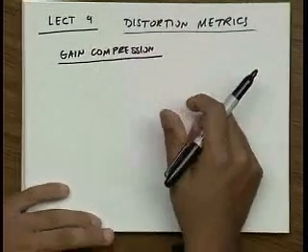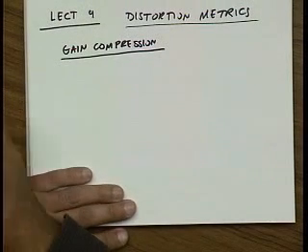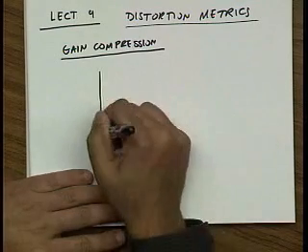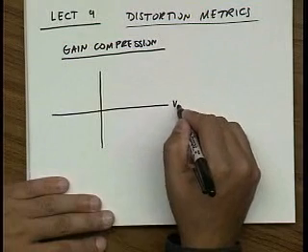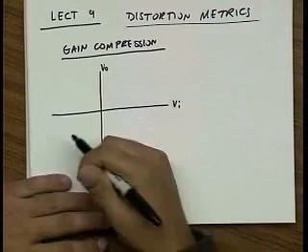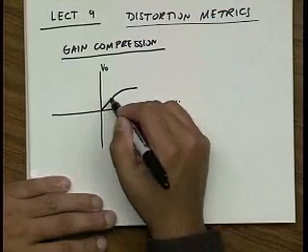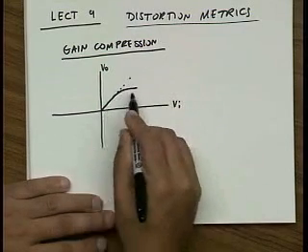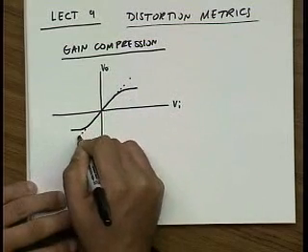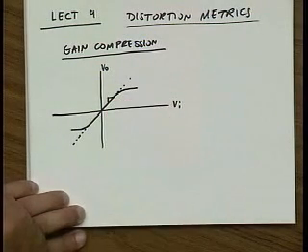Now the idea of gain compression is very simple. If you go out into the lab, in fact I encourage you to do this, take a commercial amplifier and plot the power gain. Well, first plot the output voltage as a function of the input voltage as you vary the input. So this is the input, this is the output. And this could be an AC signal, it could be a low frequency signal, but what you'll find, as we discussed last lecture, is that this output will eventually compress. And likewise in the negative direction it may do something similar. And so the apparent gain, the gain is proportional to the slope, reduces.